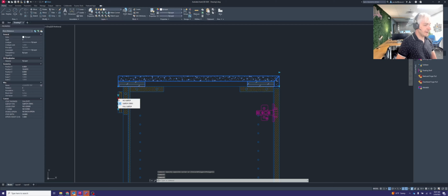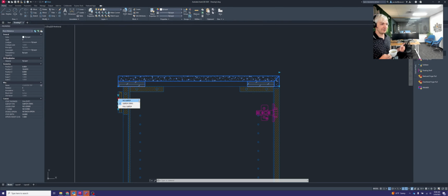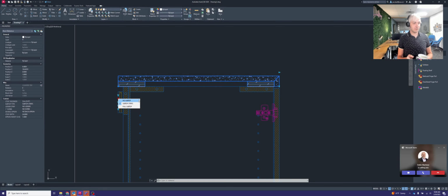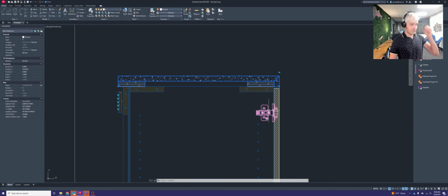Moving on down the list, you have subtop options. Sometimes you will not need a subtop. That is very rare, but in cases of having a 3 centimeter thick counter, you may not need one. If you have a standard countertop, let's say it's 3/4 of an inch like veneer, laminate, or 2 centimeter stone, you will also have the subtops here, which can be subtop strips or full subtops.